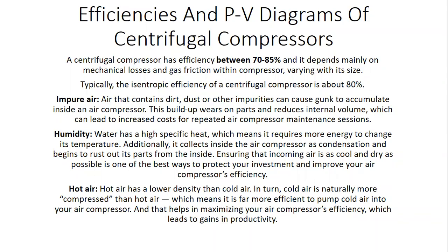All right, then humidity. Water has a high specific heat, which means it requires more energy to change its temperature. Additionally, it collects inside the air compressor as condensation and begins to rust out its parts from the inside. Ensuring that incoming air is as cool and dry as possible is one of the best ways to protect the investment of your compressor and increase its efficiency.